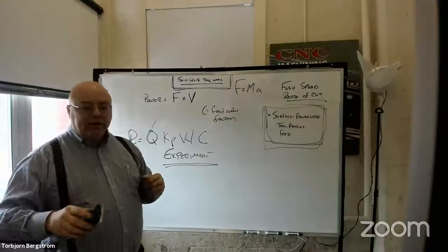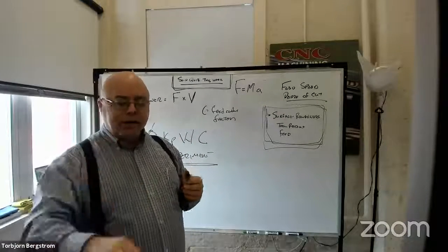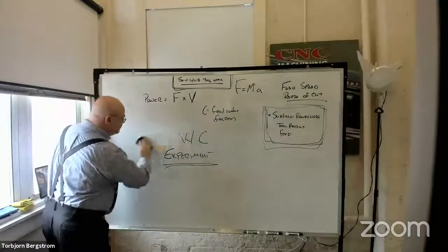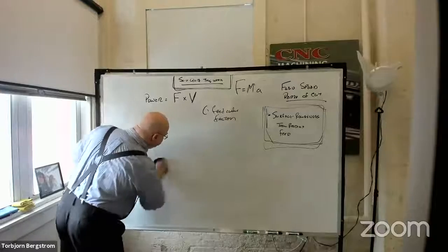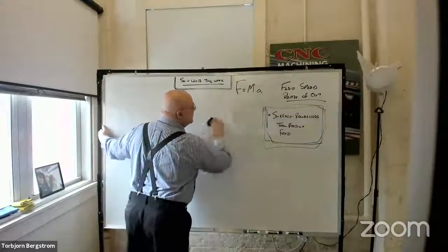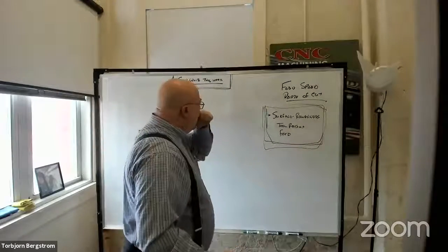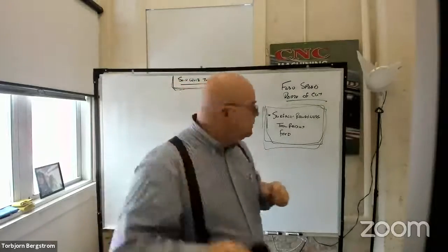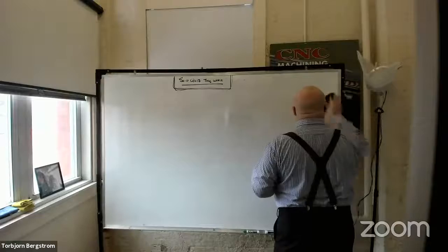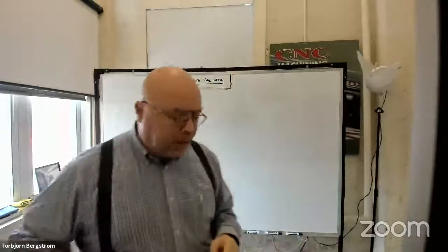It won't tell you whether the tool is about to explode, but it will let you know whether the motor is going to stall before I get finished making my cut. So you can estimate that using the information that people found experimentally and published in the Machinery's Handbook. But let's see if there's any other way we can find out about those cutting forces and thus the power.